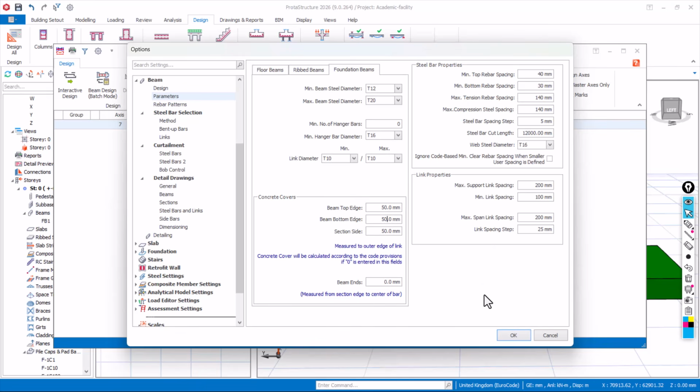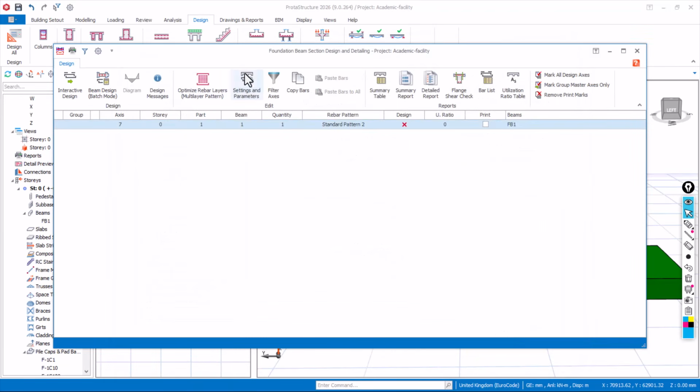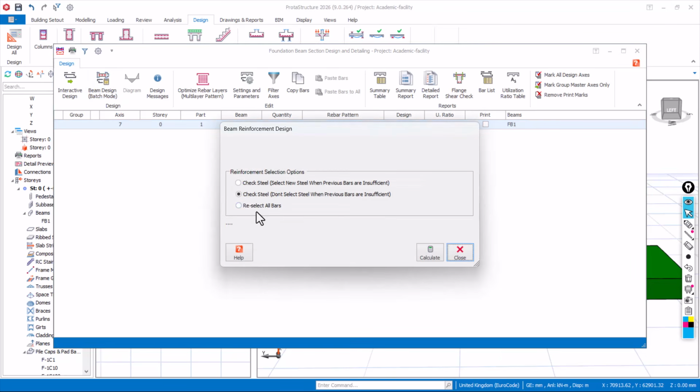Although there's some things you like, but I think I explained that much on the design. But I believe you already know these ones on the course video. So once you've done your settings in that place, you then come here and click on what? Batch design. And then make sure you click on this option here, click on what? Calculate. Once you've done that, wait for it to finish up and then click on what? Close. You can now see that our beam is now designed.